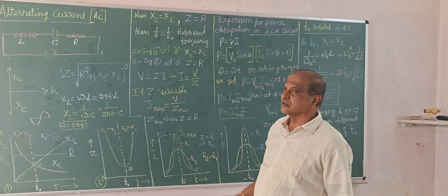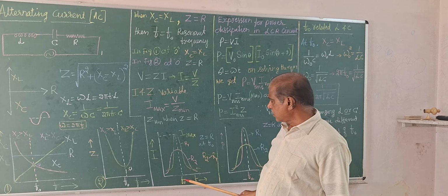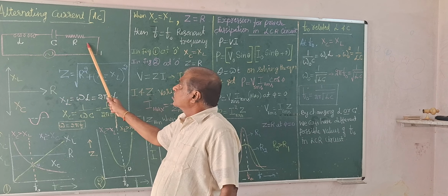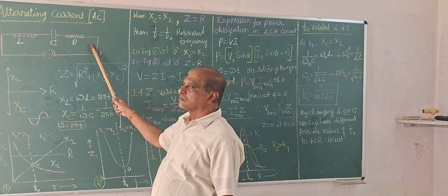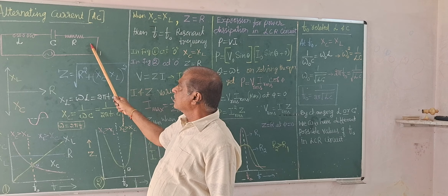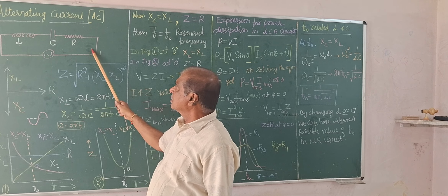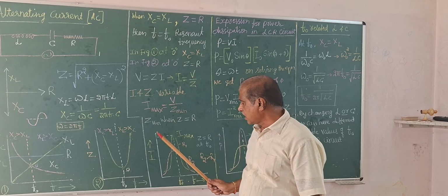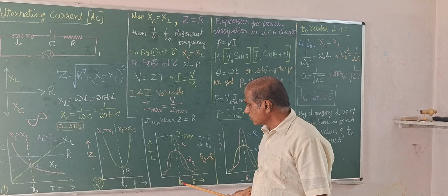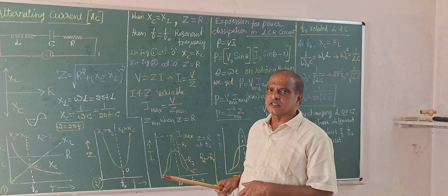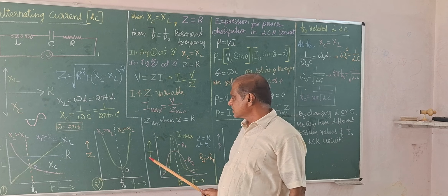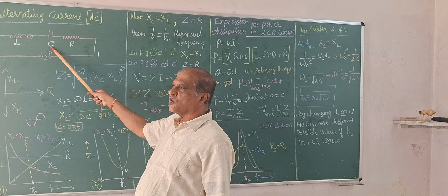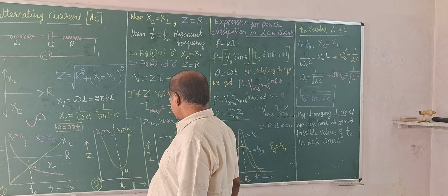Only the AC current of this F0 passes through a circuit without any difficulty, without any restriction. It can easily pass through which current? The AC current of this frequency. What about AC current of other frequencies? Other frequencies are restricted because current flow is maximum only for this.